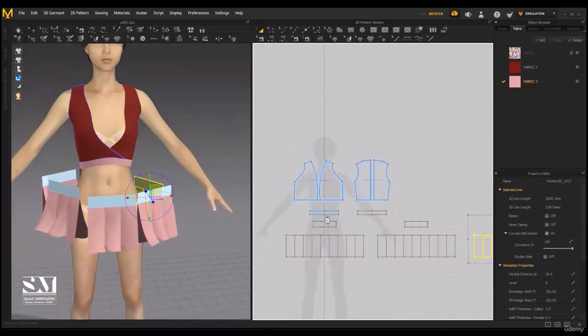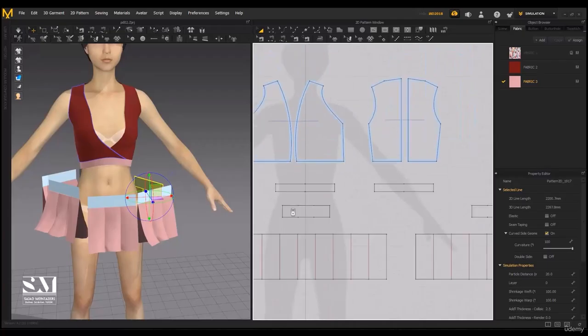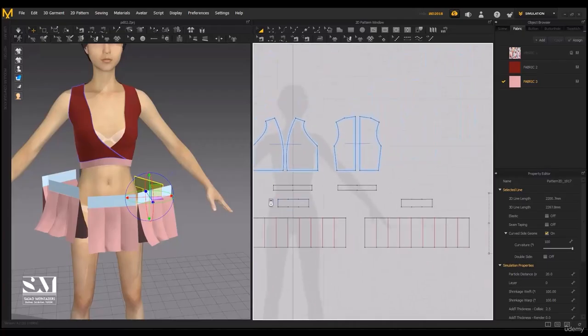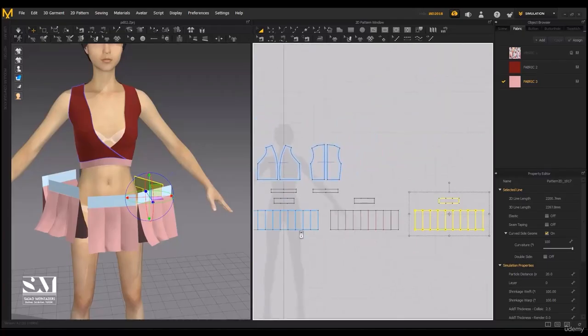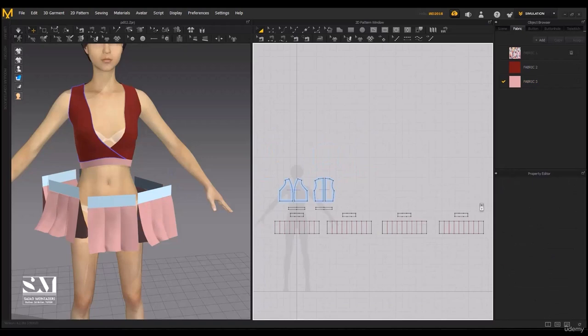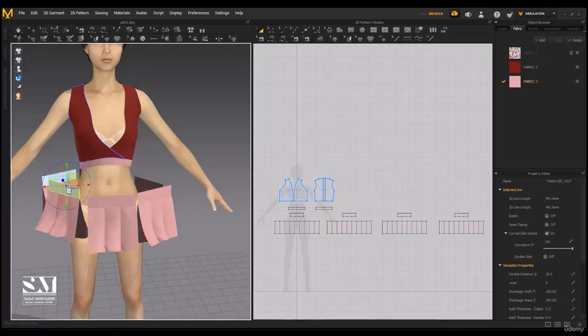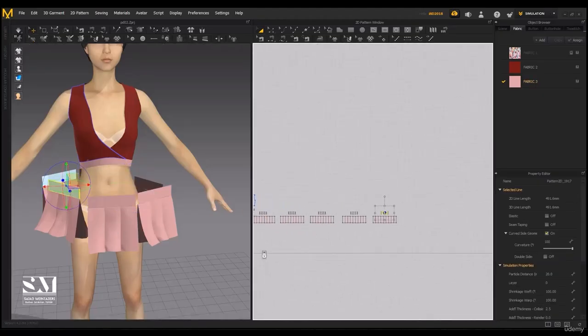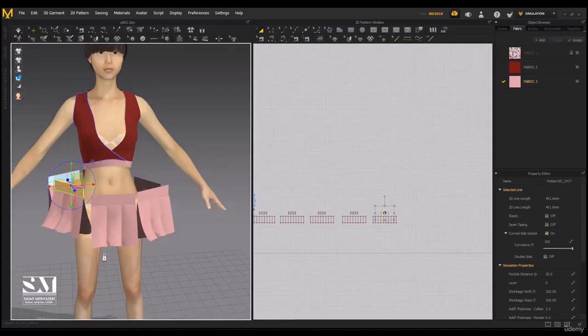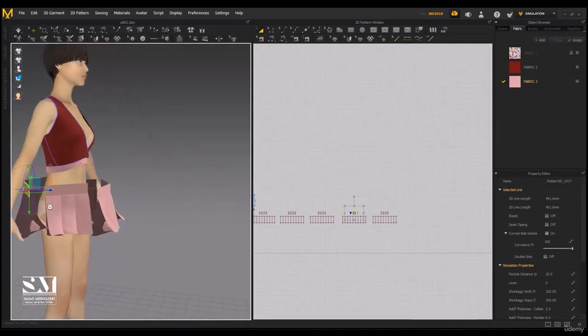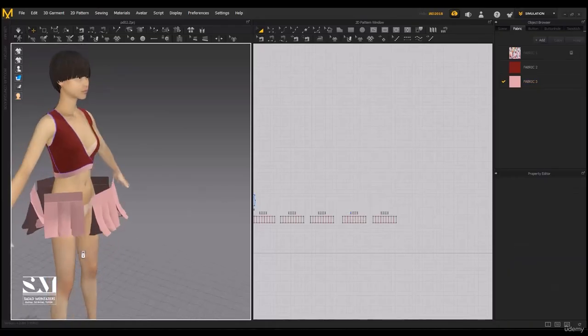Next, we can sew these pieces together. And here I'll start from this section. At this stage, we don't need freezing enabled. I can temporarily select all of them and press Ctrl plus K to unfreeze. If some pieces don't unfreeze, select them individually and press Ctrl plus K again for each one. The frozen ones can be recognized by their pale blue tint.